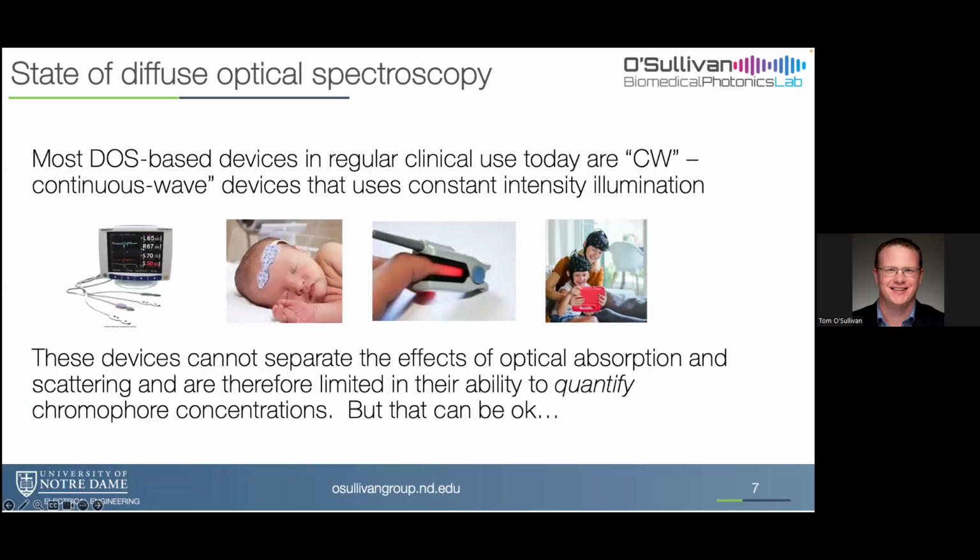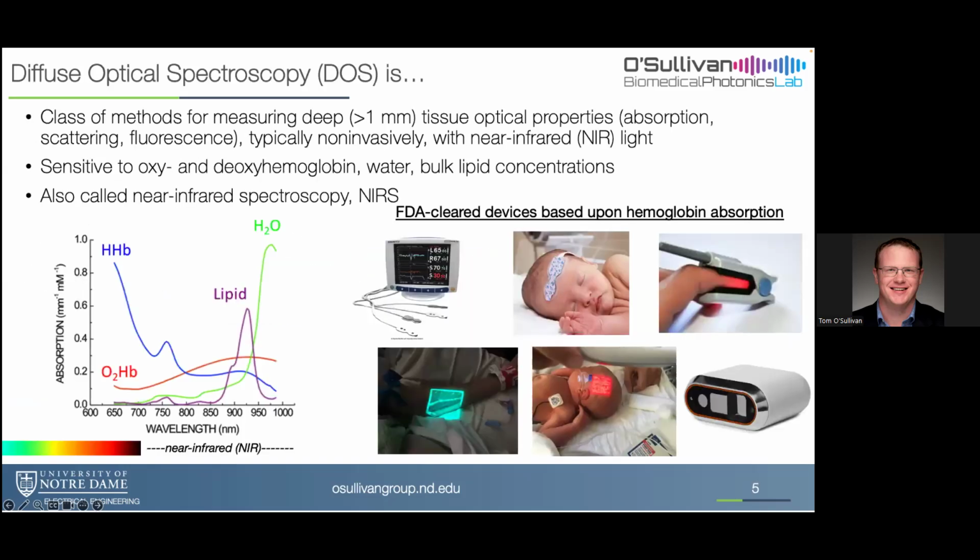So if you're going to measure changes in oxygenation, you're going to need two wavelengths. Typically in pulse oximeters, you're on either side of the isosbestic point, typically around 660 nanometers and 940 to 980 nanometers. Of course, you have a choice of wavelengths. Would you choose a different wavelength? Or just think about that. Knowing what you know so far in the course, if you were to design a pulse oximeter, what might be some of the disadvantages of using 660 and 940? So a short one and a long one.